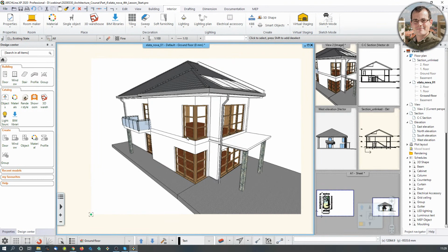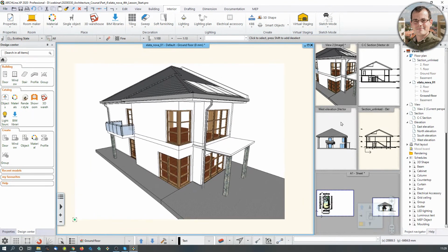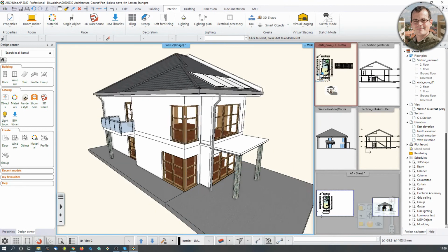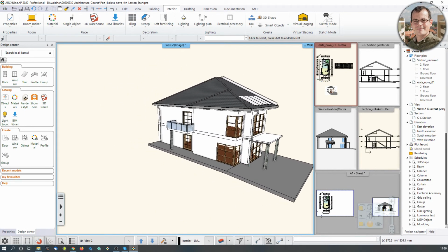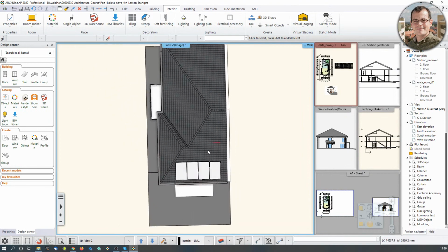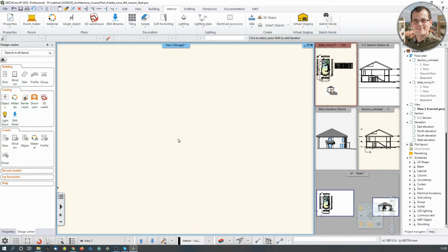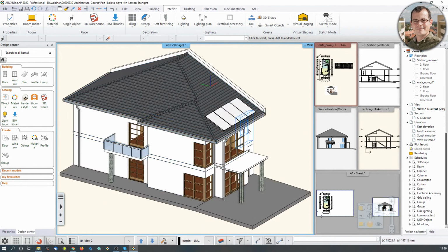Now back to the zoom to extend question. I think if that question is about scaling to fit, maybe something you want to scale to fit to your screen, you just double click on the mouse button. Not in perspective obviously, but if you are in axonometry and you are zoomed out like this, then double click pushes the content back.